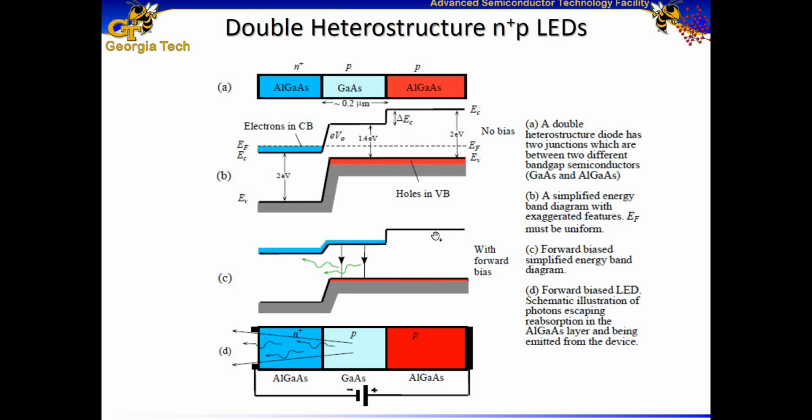However, under the application of a forward bias voltage, this barrier is reduced, and now electrons also get an opportunity to flow into this active region. We have a huge concentration of electrons and holes across the band gap of the semiconductor in the conduction band and valence band. They get an opportunity to recombine, resulting in emission of light.